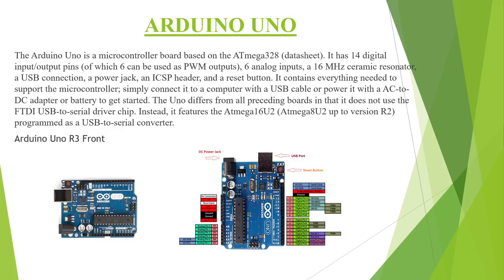Arduino Uno. The Arduino Uno is a microcontroller board based on the ATmega328. It has 14 digital input-output pins, 6 analog inputs, a 16 MHz ceramic resonator, a USB connection, a power jack, an ICSP header, and a reset button.